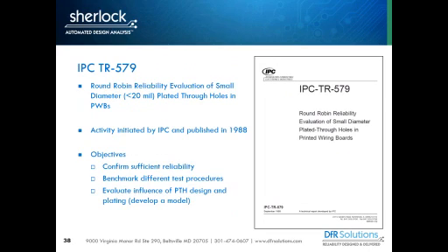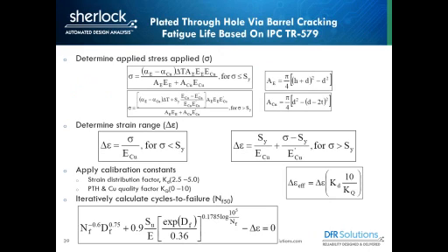When we look at plated through-hole fatigue, usually there's two different models that we have implemented. There's the classic IPC TR579 model that looks like it was developed back in 1988. And again, this is Engelmeyer, who pretty much had his fingers in a lot of different pies as far as reliability of electronics. He did most of the work on the model that is in IPC TR579. And it's worked quite well. The thing is, it tends to be a little bit overly conservative when we start getting to larger plated through holes. But here's some of the basics on that model.